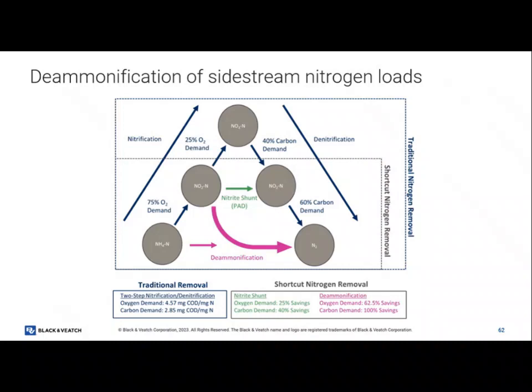It's a very difficult process to control in the mainstream because of temperatures. Temperatures we're talking about here are 35 C, so 100 degrees Fahrenheit, versus your wastewater, which is like 60 degrees. When we start talking about 100 degrees Fahrenheit, the growth rates of these two start to deviate. It's only a one-day SRT we run in these reactors, and that way we can maintain AOB at a one-day SRT, but NOB get washed out because of the growth rate.